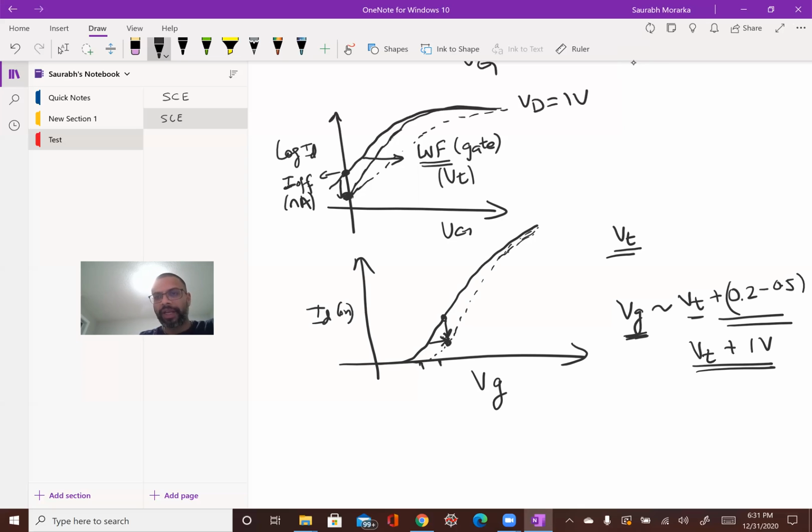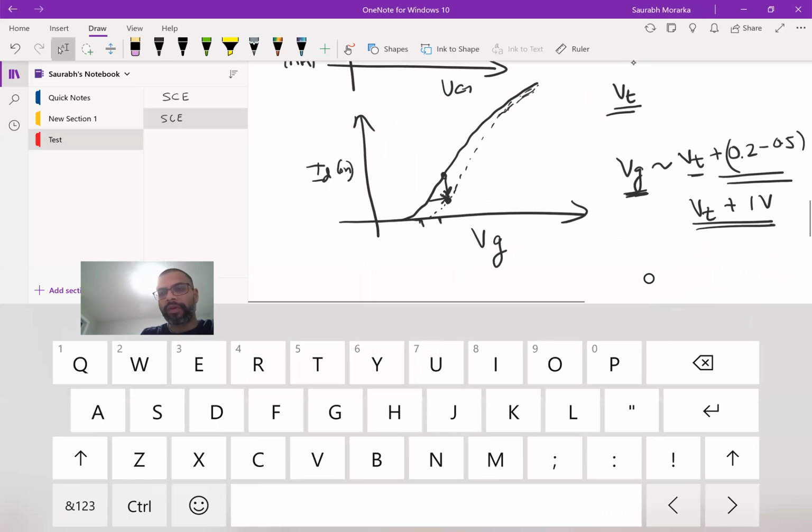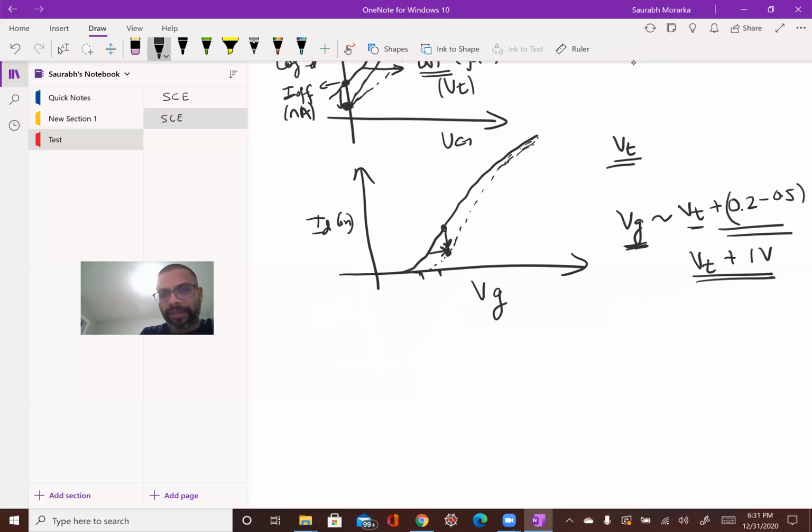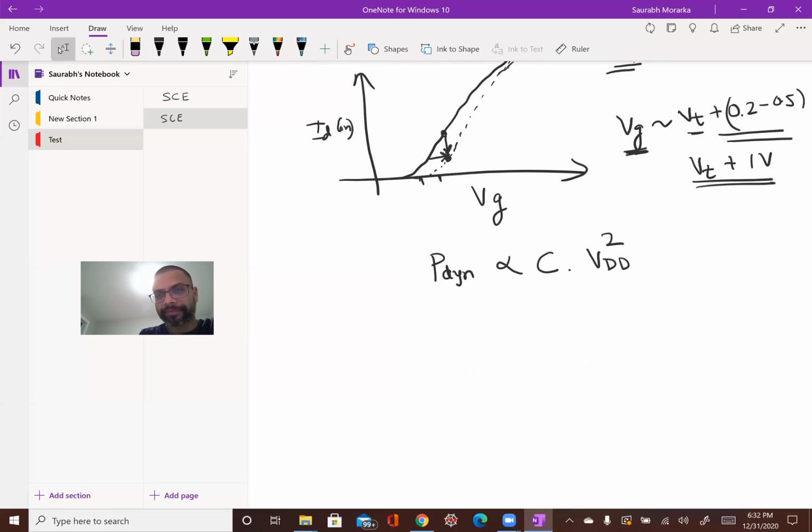Now the question is, why do we care about the operating point of the gate voltage near the threshold voltage? And that has to come down to how, as Moore's law has scaled, the way to reduce the dynamic power of a circuit, which is given by the capacitance of the devices times the supply voltage squared, right? So usually the technologists have been scaling this VDD down more and more. And what that implies, to be able to reduce the dynamic power, is that low gate voltages, which are especially near the VT point, are the most vulnerable.